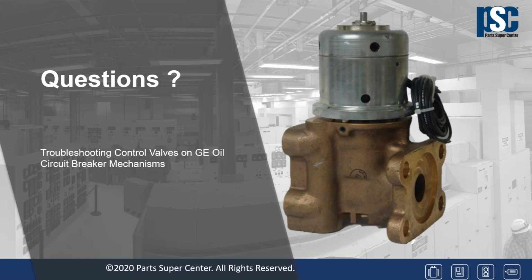So the standard also says that you have to be able to jumper the low pressure lockout contact and get 1 additional operation. So we go ahead and vary the operating pressures and the operating voltages to obtain the worst possible scenarios and make sure that the valve opens. In addition, there is a timing function that we don't do on every valve, but we do perform occasionally.